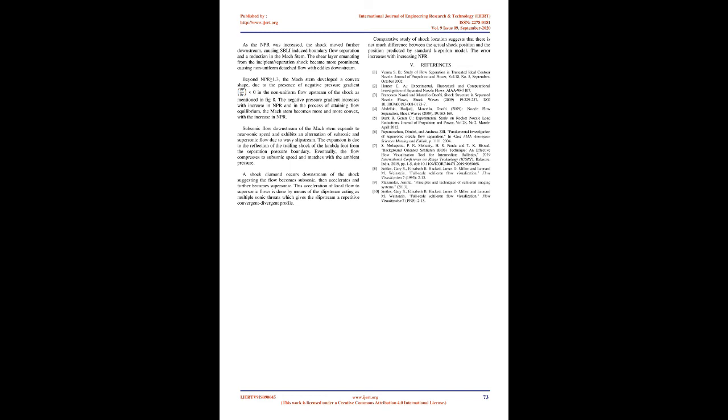Similarly, the shock locations for NPR corresponding to 1.43 and 1.7 are shown in Fig 14, C. Fig 14. Variation in flow properties across the shock wave. A. Static pressure for NPR equals 1.2, B. Static velocity for NPR equals 1.2, C. Static velocity comparison for NPR 1.2, 1.43, and 1.7. I. Comparison of shock location. The locations of shock, normal part of Mach stem, corresponding to NPRs 1.7, 1.43, and 1.2 obtained using experimental methods and computational simulation are shown in Table 3.